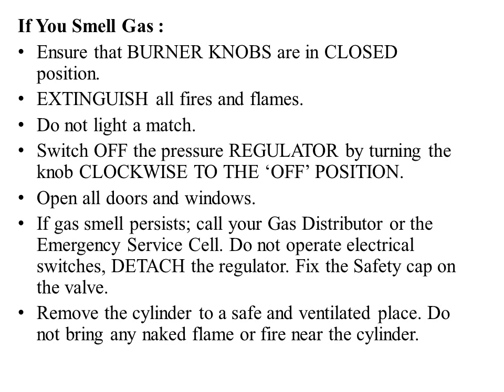Open all the doors and windows, and even after doing all this, if the gas smell persists, we should call the emergency service or the gas distributor or a person who is qualified to take up such jobs. Of course, do not operate electricity, just because if there is a gas leakage in that area, it may cause a fire. Next, remove the cylinder to a safe and ventilated space. Do not bring any flame or fire near the cylinder. So these are the steps that have to be followed whenever there is a leakage.